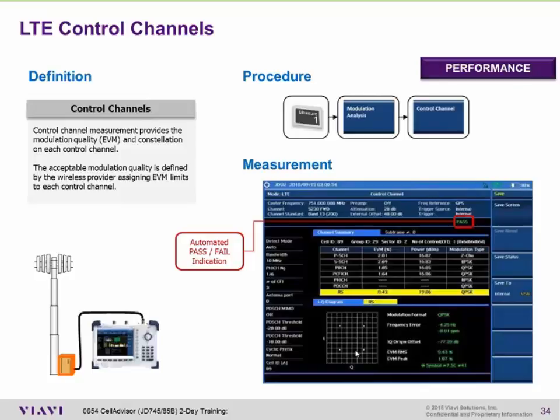What we came to realize was that when both antenna elements were transmitting, instead of getting 4 points of QPSK, these 4 little dots, we had 4 perfect circles. But it was only when both transmit antennas were transmitting. We'd gone to hardwired connections at the DAS system as well as on the output of the radio, and both transmit signals were perfect. We actually turned off one transmit, letting the other one on, and the signal was perfect. We alternated, swapped which one was transmitting. Each one individually, the signals were perfect.